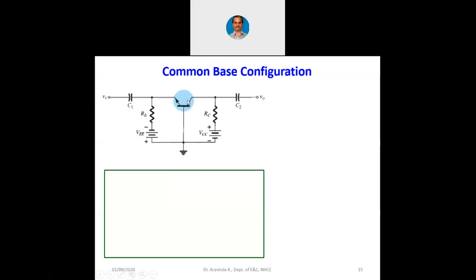Always remember that this transistor is kept at half on. Now it can always turn into either fully on or fully off state by the effect of the input signal which we apply, and that input signal is always AC. Now because of this, even emitter can be input. You should always think of the amplifier circuit in terms of AC and not in terms of DC. Otherwise, if you keep thinking in terms of DC, immediately you will come to a conclusion that as the arrow mark at the emitter is toward the outside, how can current go inside the emitter?